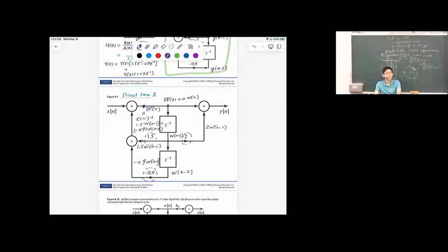That's the way we, again, after some simple but careful analysis, we found that this intermediate variable should equal x plus 2 feedback terms. We have feedback right here. Is that clear? The intermediate signal itself can be expressed as the sum of input plus 2 feedback samples, 2 samples that got fed back to the node right here, and they sum up with the input.